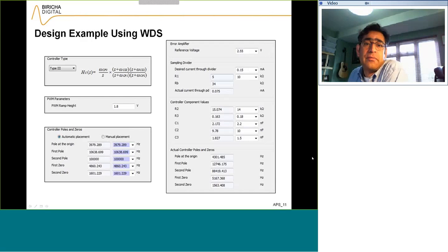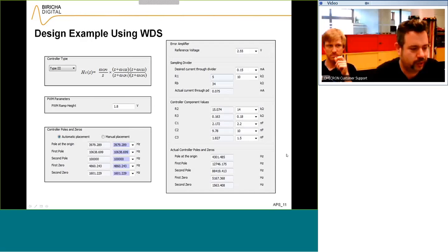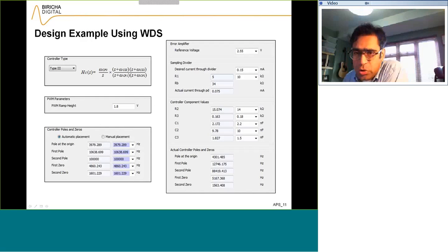Ali, we got the first question on the chat function. The question is, what about DC bias and cap value derating, assuming we need to enter derated values? No, at the moment we are talking about the output capacitor, which is an enormous electrolytic capacitor. The DC bias comes into play when you are dealing with large ceramics.